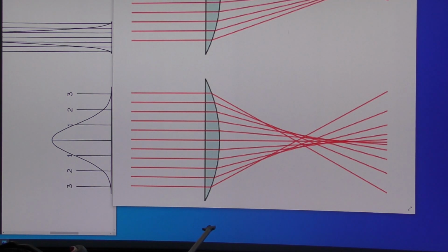We've turned the lens over so that it has really serious aberration. These rays are no longer uniform. They are going to assume an intensity proportionate to this Gaussian distribution. The ray in the centre is going to have maximum intensity, its maximum potential to do damage to material. If you expose a piece of material to high intensity for a short period of time, it will do damage. You can expose a lower intensity to the same material for a longer period of time, and it will do the same amount of damage.